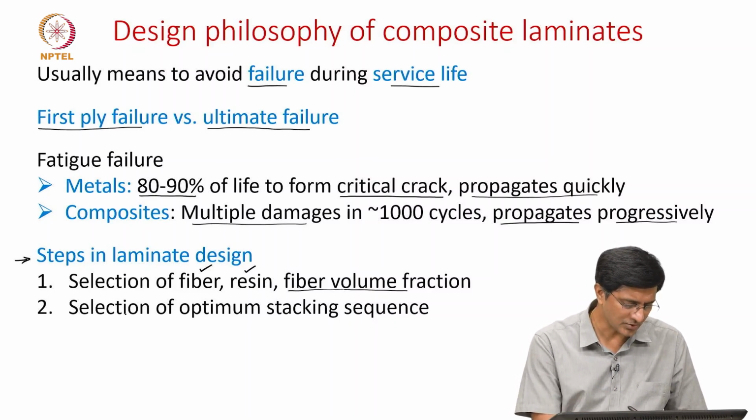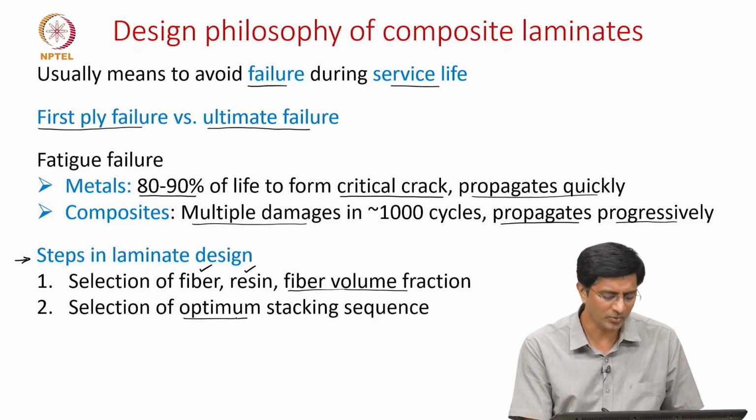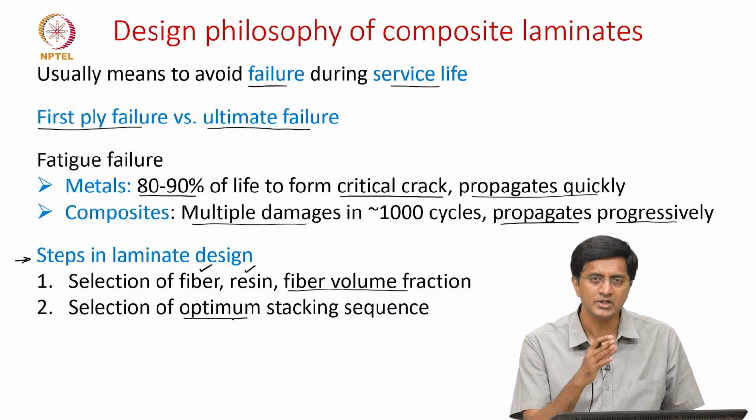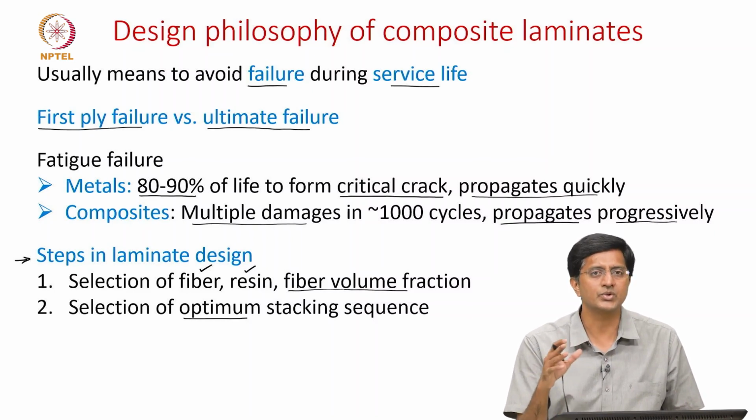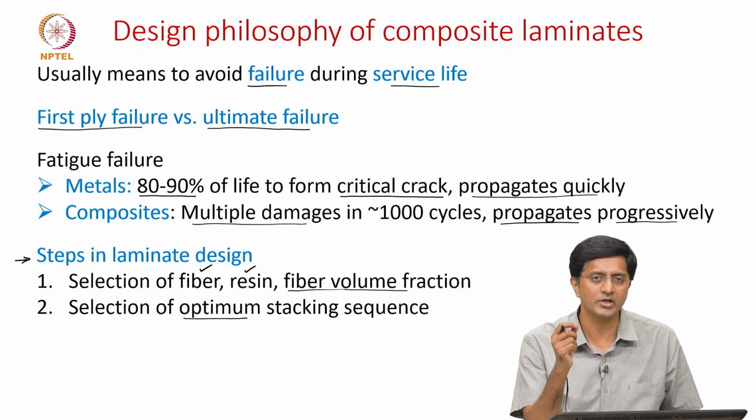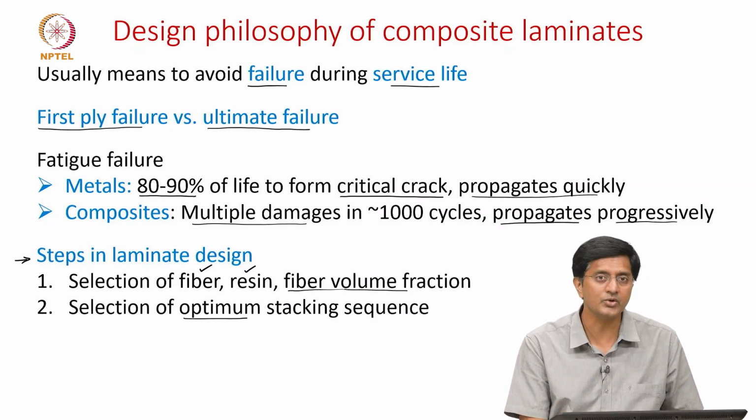And the second step is to choose the optimum stacking sequence. What do we mean by optimum here? Because each stacking sequence will have its own stiffness and strength. We need to come up with a stacking sequence which, let's say for this application, gives a minimum mass structure, meaning a stacking sequence which meets all the functional or design requirements with minimum mass. And depending on the application, the way you define optimum might change, but essentially what we are looking at is